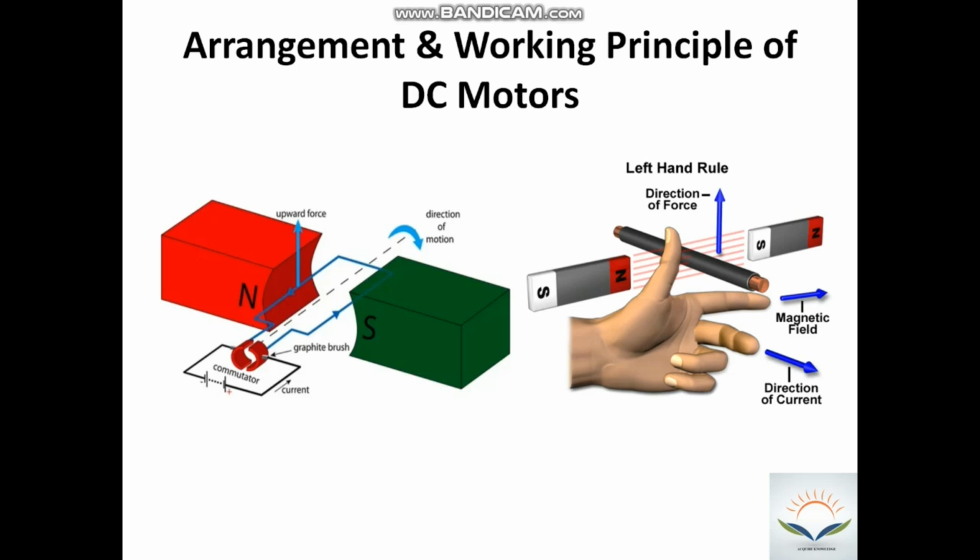To understand the arrangement of the DC motor, let's take two bar magnets whose opposite poles face each other, apart. In between them, let's place a copper wire loop whose ends are terminated at the commutator. The brushes are in contact with the commutator assembly, and the external DC source is fed to the carbon brushes, which in turn supply the copper wire through the commutator.